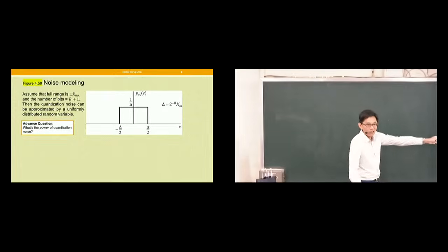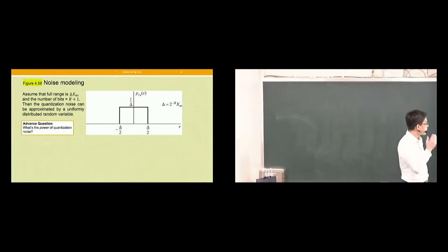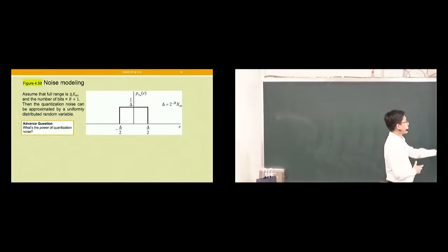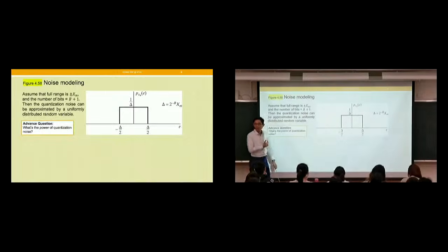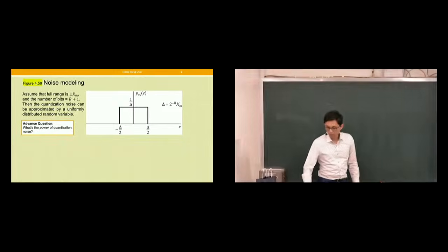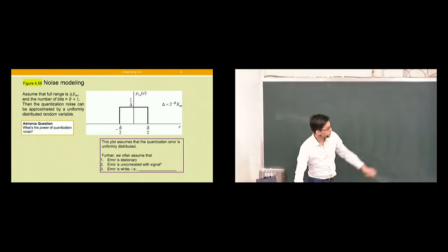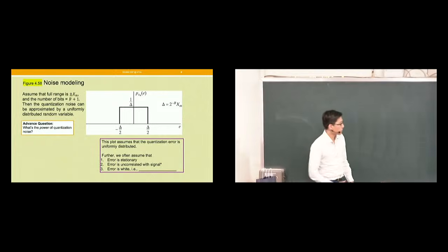But it turns out it can be further developed into probability. So quantization noise is very conveniently regarded as a random variable in that its distribution is approximately uniform. Later we can even discuss what we mean by noise.